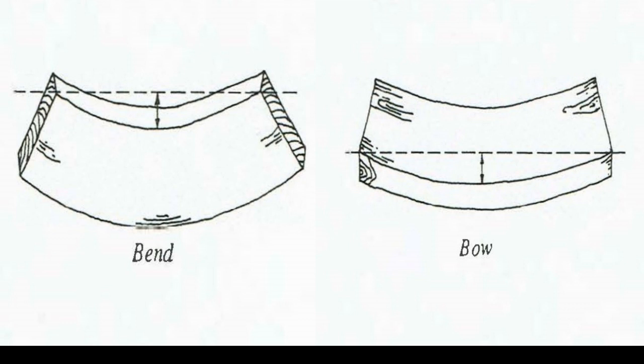If it happened to be on a board that's on the edge of a framing piece, and we'll go over this momentarily as well, you'll typically have to try to bend it or push it to help fit within the guideline of the sheet good that you're going to eventually attach to it. Bends, however, are probably, again, one of the more difficult defects that you'll typically run into, as the board doesn't want to maintain its actual shape. If you try to use any kind of bend in the board, it's going to dramatically alter the overall structural shape of your project.